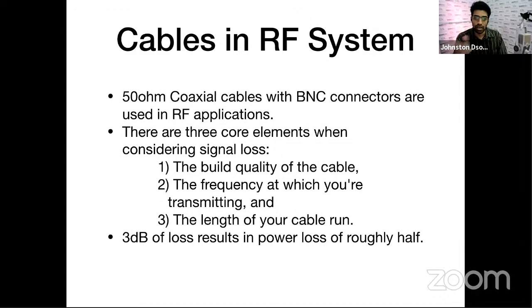Okay, RG58 is basically a lower grade cable, which is okay when you're running small lengths of cables, like maybe a few feet, that is okay. But if you're running large lengths of cable, like anything close to 100 meters, you go for the higher end cable, because the quality of the cable is going to create a big difference when it comes to long cable runs. Okay, you make sure that you get a 50 ohm cable. If you're running large distances, you get a superior quality cable. If you're running smaller distances, more inferior quality would do.